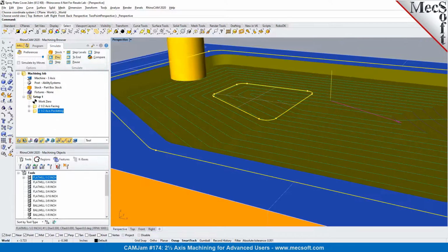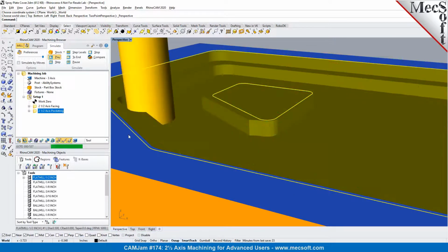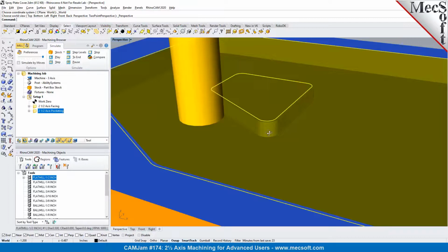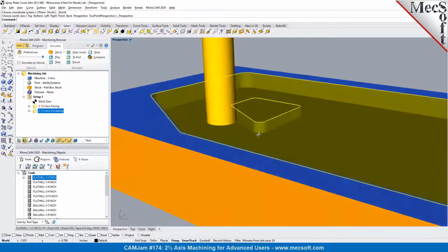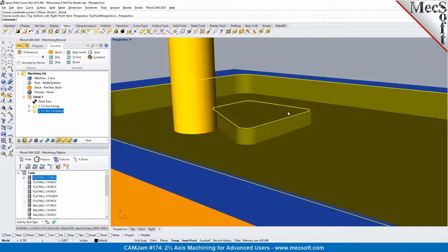One quick comment on this, Uday. I just wanted to point out that when you specify clear island tops and you specify a step over, we would adjust the step overs, in a way that you're actually clearing the island tops. So your step over that you get in the toolpath might not be exactly the same as what you specified. It will definitely be below or smaller than the step down value that you specified.